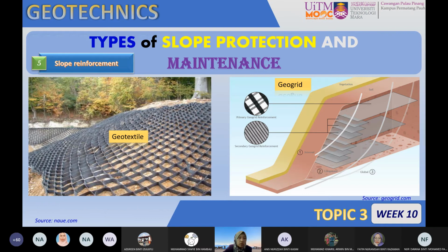And the next one is using geogrid or geomembranes. Geogrid and geomembranes are something you may see on the slope face, let's say after the slope has failed and no repair works have taken place. Temporarily, we can place the geomembrane to retain the slope from failing as a temporary repair work, or you can use geogrid and geomembrane for long-term repair work, using the appropriate method of construction.